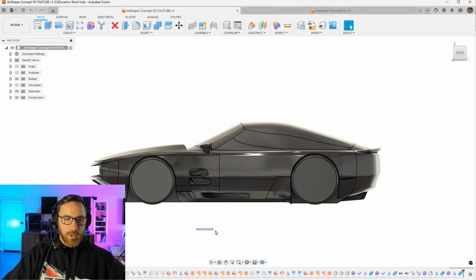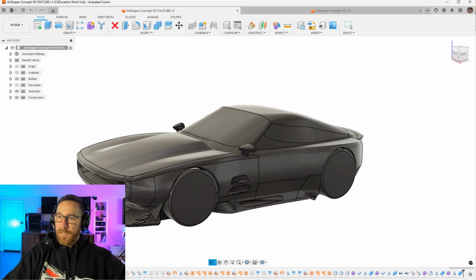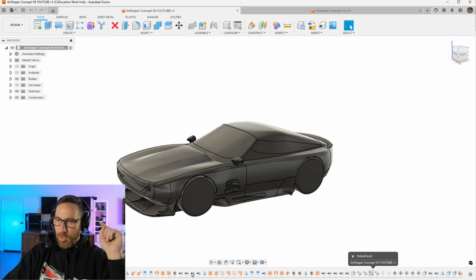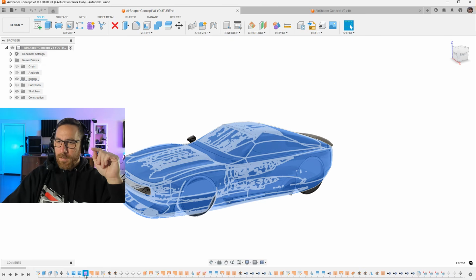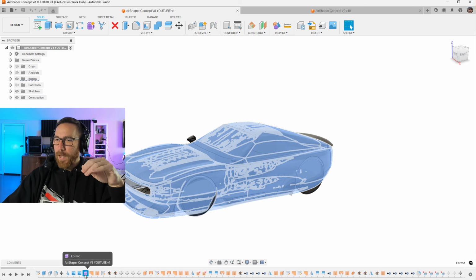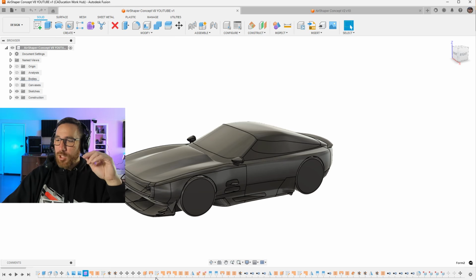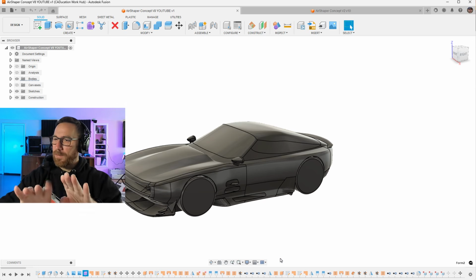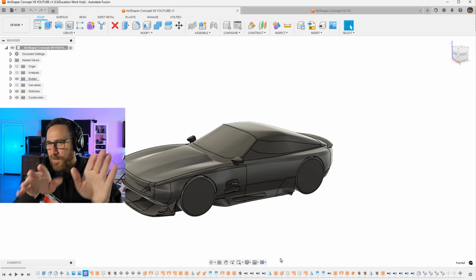In the description of this video, I'll include a link to this version 8 file. So if you want to take a look at it, play with it, or put it into AirShaper yourself or make some changes, I will caution you that if you do go back to the original freeform body and make changes, there is a good chance that stuff will break. I say that because of the way that some of the surface tools work in Fusion. For example, if you trim and you select the side of the model that you want to trim away, sometimes when it goes through the rebuild process, it flips those.